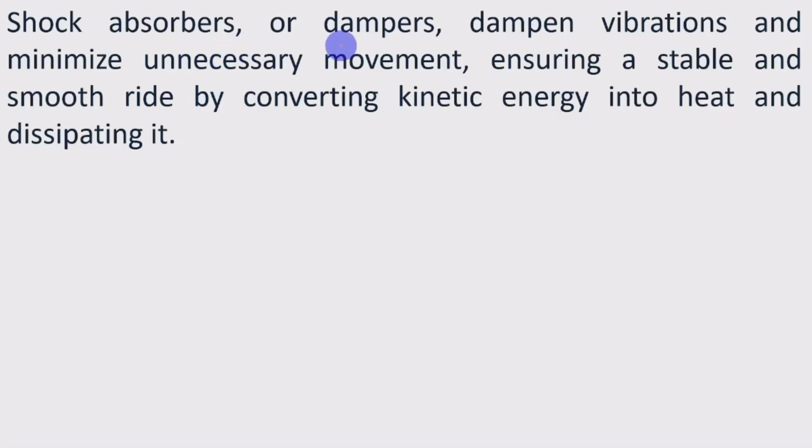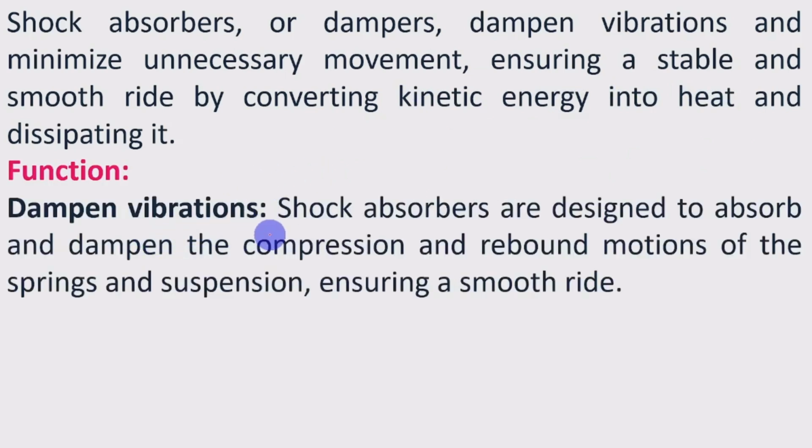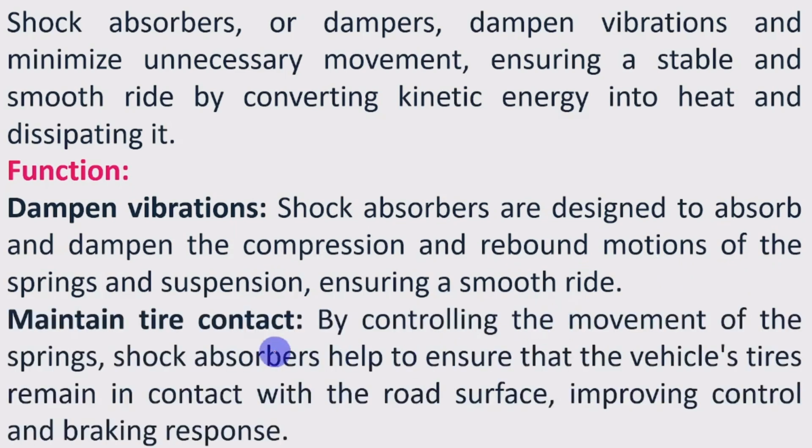Shock absorbers or dampers dampen vibrations and minimize unnecessary movement, ensuring a stable and smooth ride by converting kinetic energy into heat and dissipating it. Function: dampen vibrations. Shock absorbers are designed to absorb and dampen the compression and rebound motions of the springs and suspension, ensuring a smooth ride.